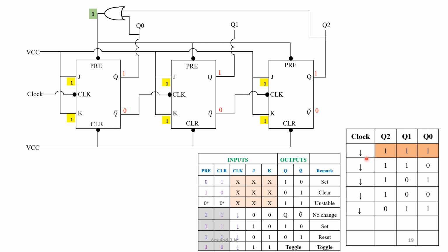Now the clock pulse we are going to apply, then it is going to shift to the next value. So here is the next value we have got, so that we can observe over here. So it is 1 1 and 0. Correspondingly, you have to make observation of the Q bar at each stage, and then at this stage we are going to apply the clock pulse. It will move to its next value. So it is 101, we are in the regular down count operation.